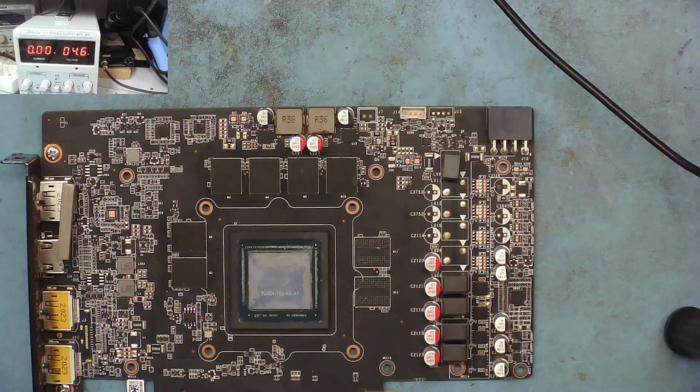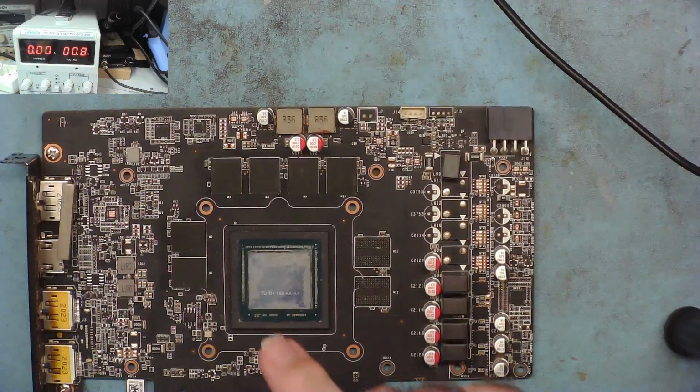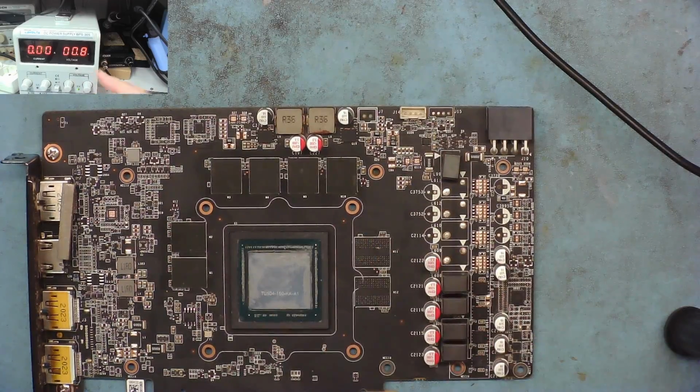I have my bench power supply. Now I need to set the voltage on this to be lower than the supply voltage for the GPU. That's the only way to be safe. It needs to be lower. And then I can set the current to flow whichever I wish. So I can now effectively short the two leads together, and I can dial up whatever current I want.